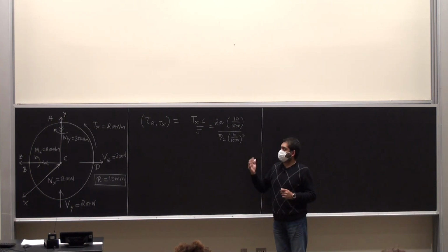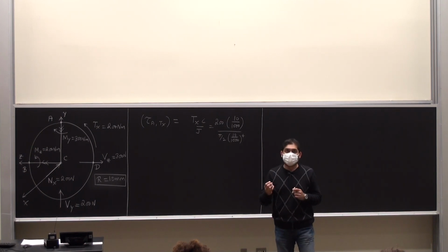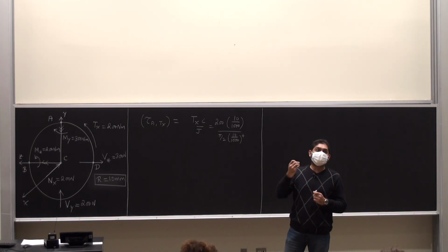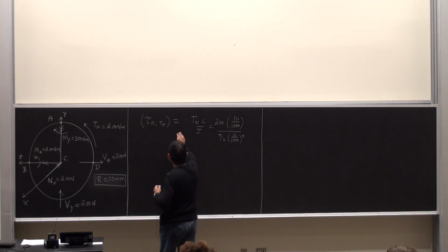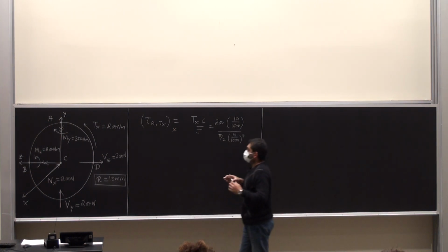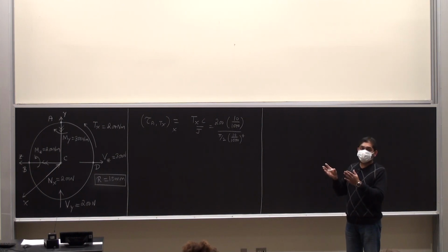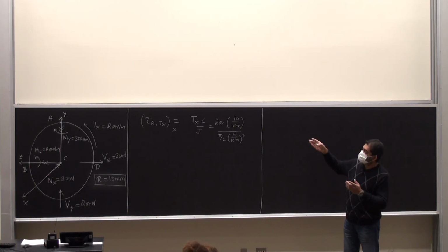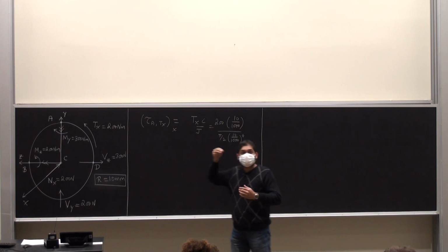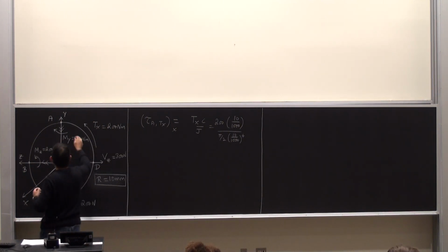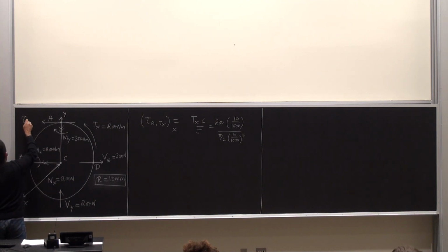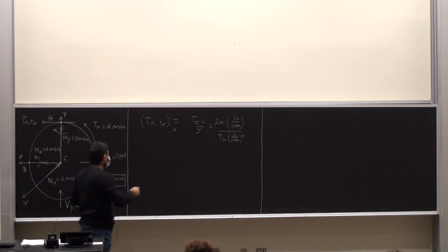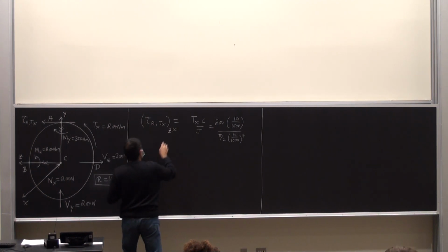We were able to write the subscript for the shear stress. The second subscript is always the direction of the area normal, which is coming out of the page in this case, which is the x-axis. The first subscript is the direction of the shear stress itself. At the point A, due to Tx, the shear stress is going to be pointing to the left. So this is going to be zx.